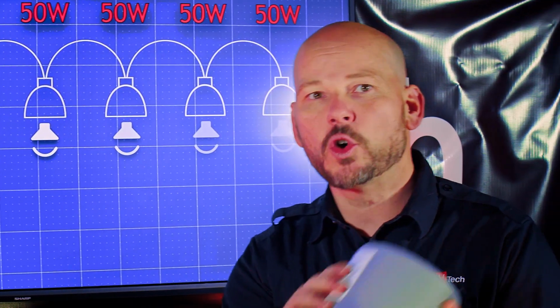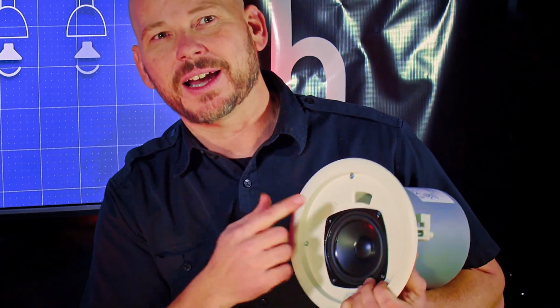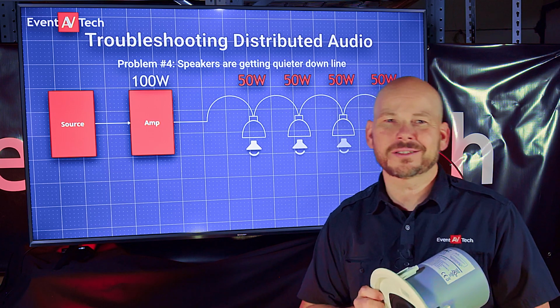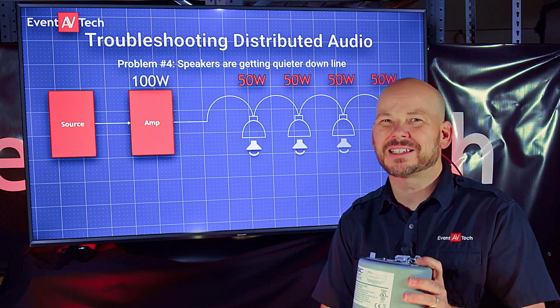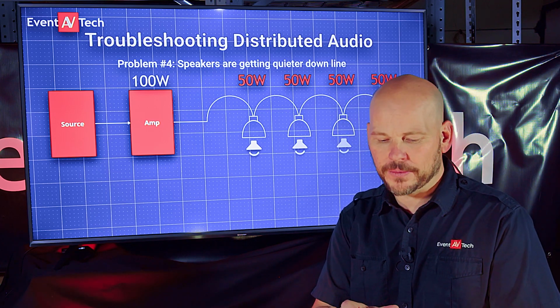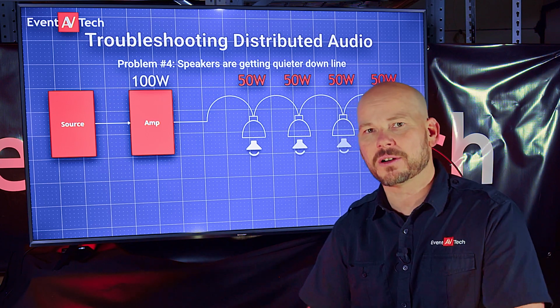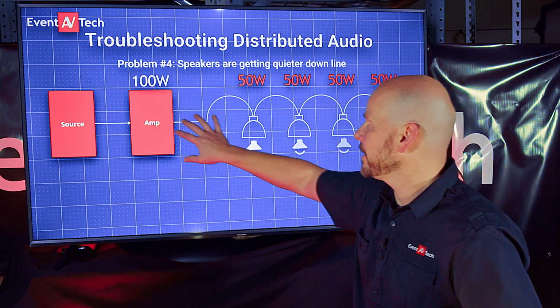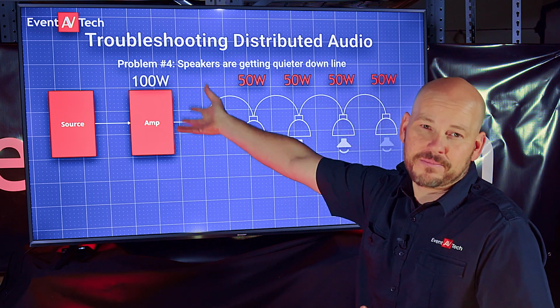So that's normally going to be that you've got a tapping problem. Whose fault is that? Well, installers, we can make mistakes, but if it's designed improperly, if the person who put the thing together doesn't tell you what to tap it at, or they tell you to tap it at one setting, but there's not enough power in the amplifier, that's going to become a problem. Well, then how do you fix that?